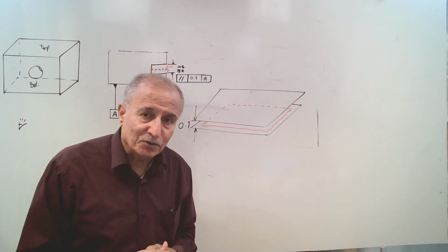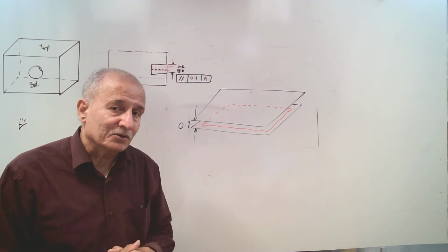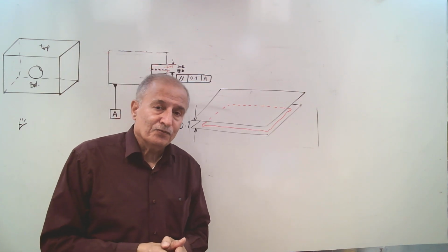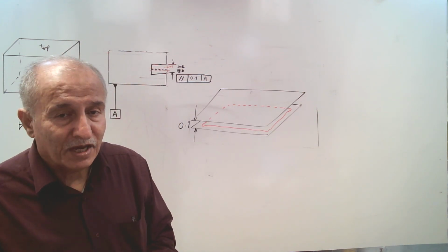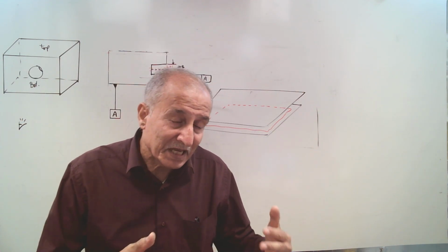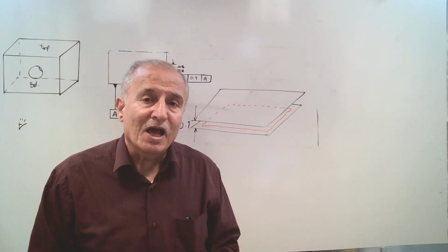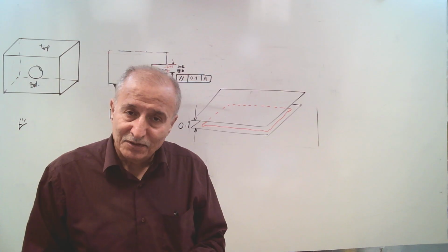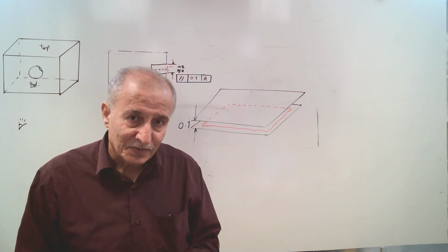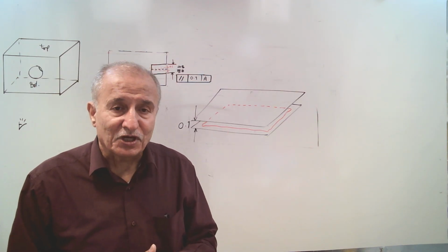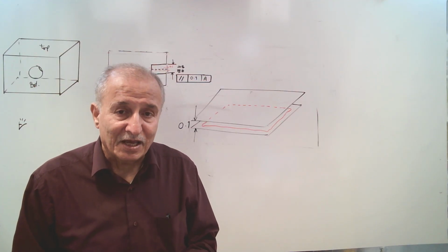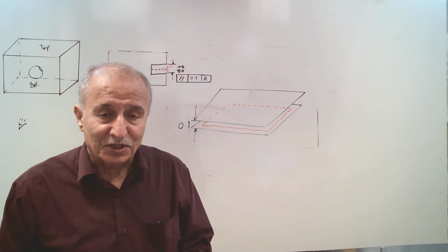Then, orientation can be applied to a planar surface or can be applied to a feature of size. When we use orientation, here it means parallelism. Applied to a planar surface, it can have the T modifier. When applied to a feature of size, it depends. If it is an axis, L, M, P modifier.